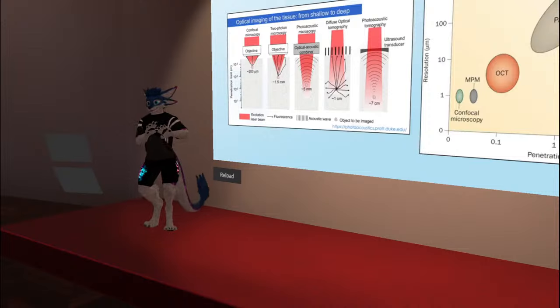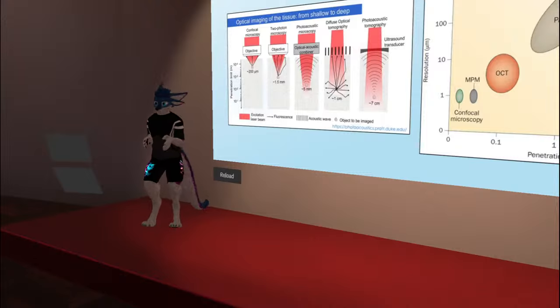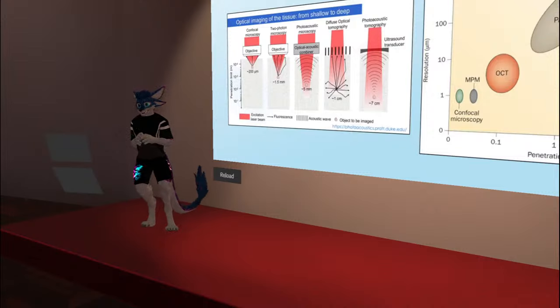to the point where a lot of UV lenses, especially in high intensity, and keep in mind, I'll also preface, this is a different ballgame than extreme UV. Extreme UV is a different thing. They do different things with their optics. This is not that. But in regular UV town, a lot of times lenses are just consumable. If I buy a high power UV laser, a lot of the lens modules in there are designed to be removable. They'll have like a 2,000 hour shelf life, and then you swap them, right? So this is a real problem in this kind of regime.